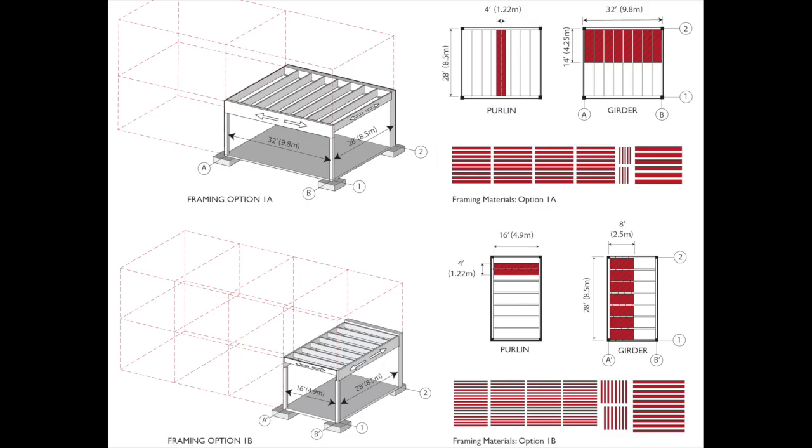And again, so what else can we learn from this? In order to get our estimates in terms of the size and depth for it, in red I'm showing you the tributary area that we would need to have in order to determine the size of the purlin. That's the purlin's tributary area. Or tributary area for the girder, in red showing you what that tributary area is. You'll see how this is important later when we collect the loads.